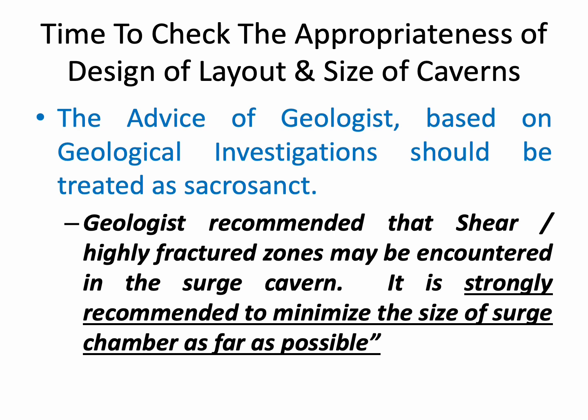Based on the only borehole done in the Downstream Surge Gallery, geologists could infer from the limited data itself that shear and highly fractured zones may be encountered in the surge cavern. So they strongly recommended to minimize the size of surge chamber as far as possible. This advice should have been taken to be sacrosanct.